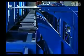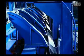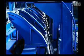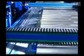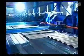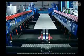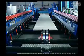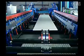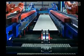The flange sheets prepared for the respective order are stacked in appliances at the sides. Grasping devices drag them into supply position. Together with the ready-made, shaped and corrugated flange sheets, they are transported longitudinally to the assembly station. There they are taken up in open position. In a fully automated process, roller jaws adjust the flange sheets and secure them in the correct position. The flange sheets are hydraulically moved to the center and pressed to the web plate.